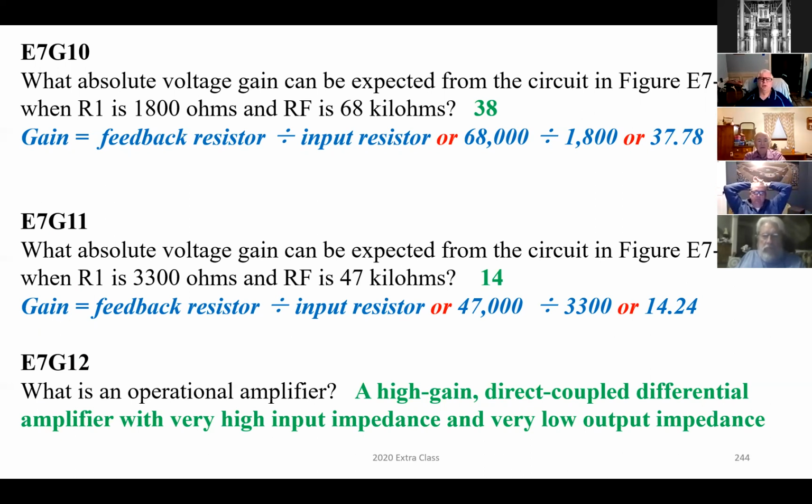Okay, what is an operational amplifier? A high gain, direct coupled differential amplifier with a very high input impedance and a very low output impedance. And what they mean by differential is you have both a positive and a negative input.